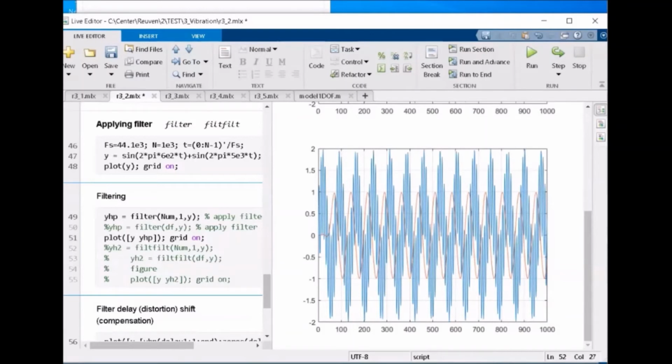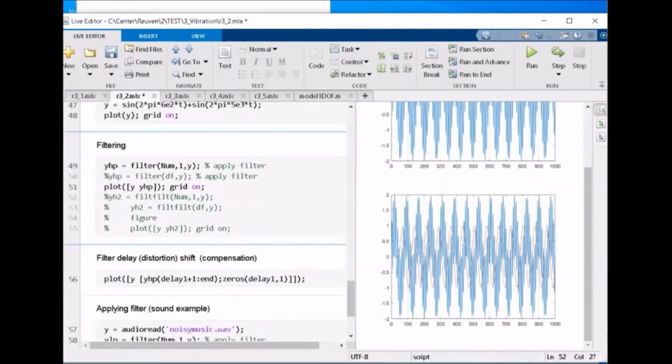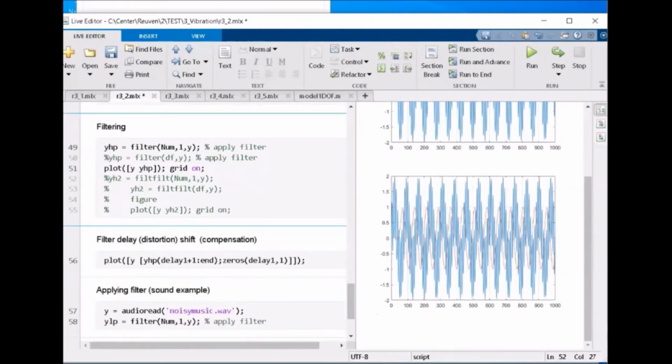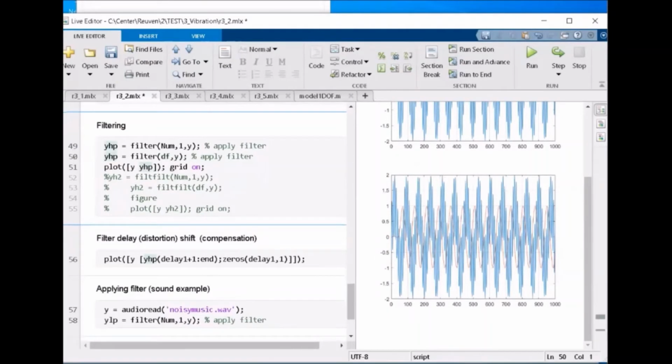If we work only with one signal, it's not so important. But already we spoke about phase shift. When we have several signals, we need to know the phase shift. We just need some instrument to work without any shifting. Matlab has two ways to do it. The first way is just using the same filtering, but using the command filtfilt.